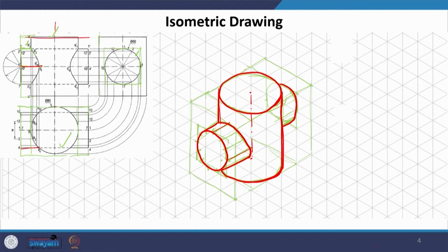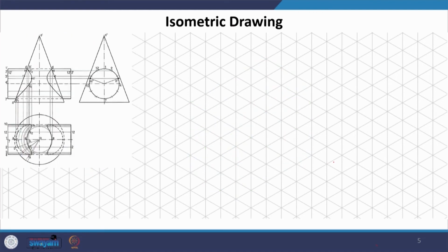This plane parallel. So, all the lines which we are drawing here, the points which we are drawing here, are being derived from the orthographic projections which we have already got. So, the parallel lines remain parallel, the perpendicular lines will appear in connection with the other one, the non-isometric lines. So, that is what we have done here, and we have arrived at this example.